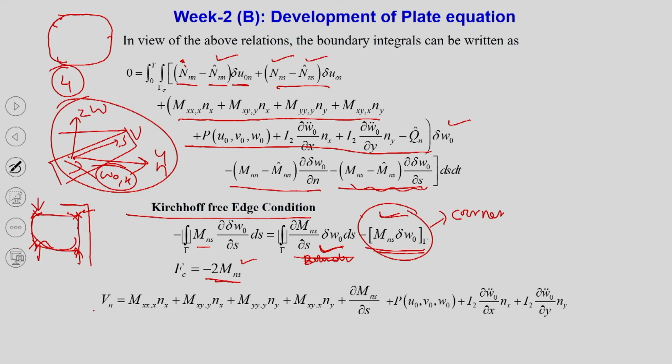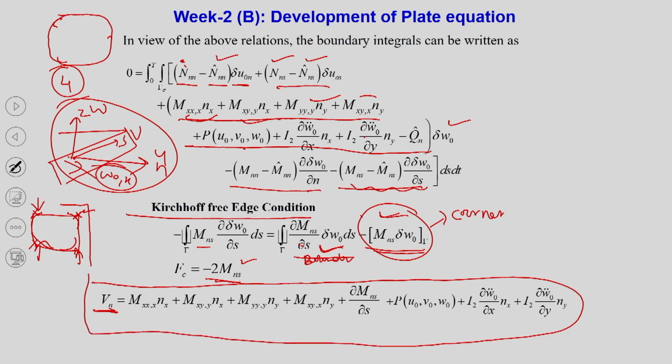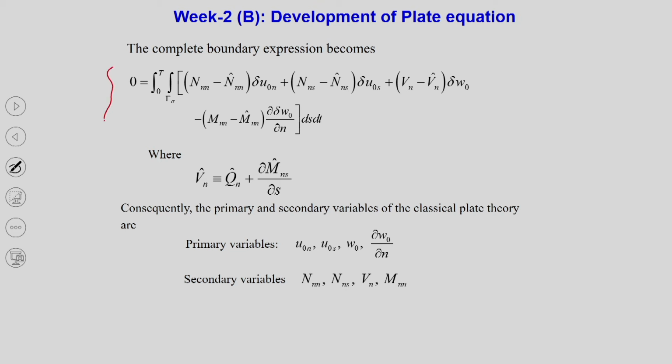and contributed further to the boundary conditions. So, now again defining, basically one contribution comes to here. Now, you see what is this Mn, Nx, My, Mb. Putting together, let us say this term is nothing but Vn, shear force along normal direction, or shear stress basically, the Kirchhoff shear stress resultant along normal direction. So, all these terms plus the contribution from Mns we are putting together and making it Vn. So, now our modified boundary conditions 1, 2, 3, 4.